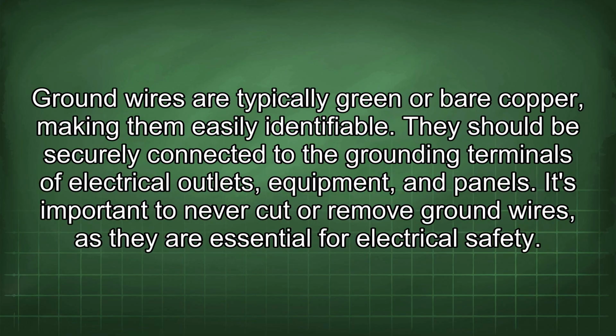Ground wires are typically green or bare copper, making them easily identifiable. They should be securely connected to the grounding terminals of electrical outlets, equipment, and panels. It's important to never cut or remove ground wires, as they are essential for electrical safety.